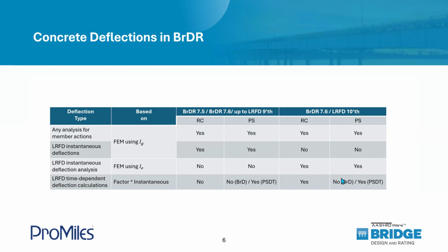Now, so we still don't have the time-dependent deflections in BrDR for PS, and it's just because the factor that AASHTO LRFD 10th edition gives us just does not apply to PS. We still can calculate the long-term deflection in the prestressed design tool, but again, it's just based on a different factor coming from PCI.